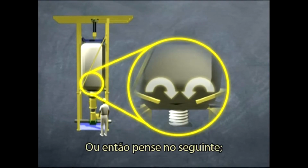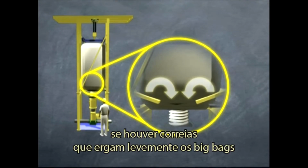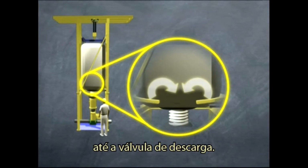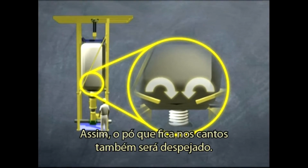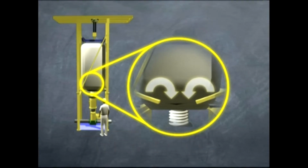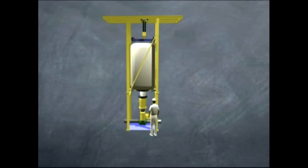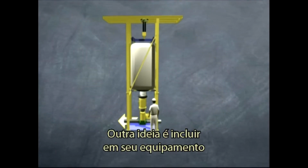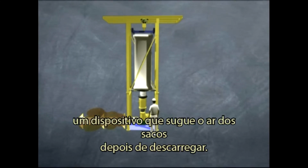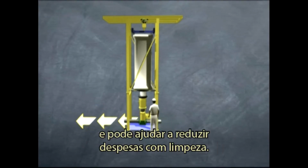Or think about this. Unloading can also become more efficient when panels are installed that can slightly push up the big bags near the discharge spout. It will push the powder from the corners of the bags to the center where the discharge spout is located. Another idea is to include in your equipment the possibility to suck the air from the bags after unloading. This will prevent cocoa dust from entering your production halls and can reduce cleaning costs.